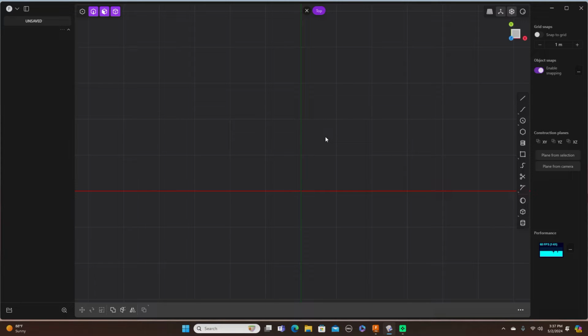First I'm going to draw a line, a 2-meter line. Each one of these segments here is 1 meter, so 2 would be 2 meters long. I'll come over here to the line tool, click that, click it right on the origin, and move it over here. I want to make this 2 meters, so I hit Tab and put 2 and double right click on that. And now we have our 2-meter line there.